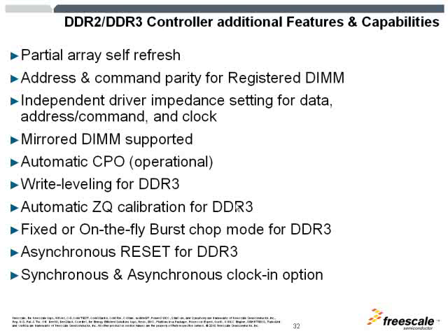Next, we have the address and command parity for register DIMMs. We have ECC available for the data bus, but there's no ECC for the command and address bus. But if you use register DIMMs, the option is available. This feature would apply to both DDR2 and 3.